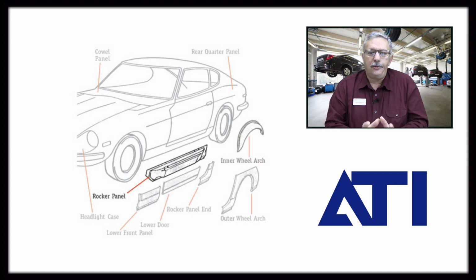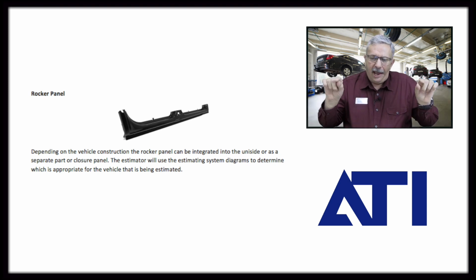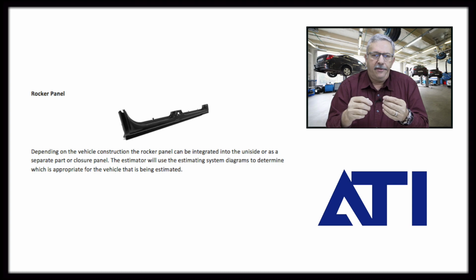A couple of things that are real important with this. These are again typically welded. They can be adhesively bonded if the manufacturer specifies that. But the important part about this is when these are put in, we're building a closed, boxed section. When we do that, we have a heat effect zone that goes behind every place you weld. Behind it, you're going to burn through the black paint that's on there, which is electrodeposition primer, EDP. When we burn that away, we have to restore corrosion protection to the panel.